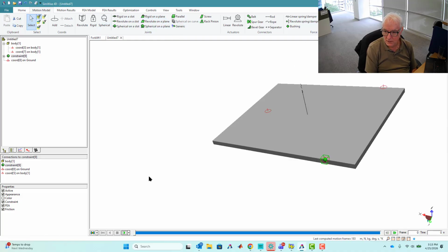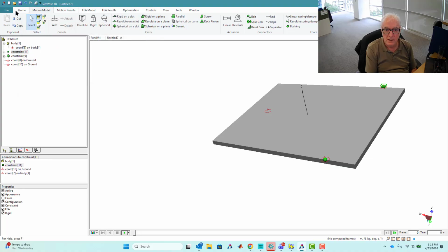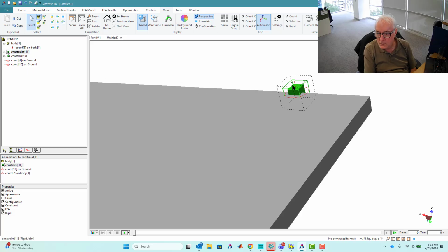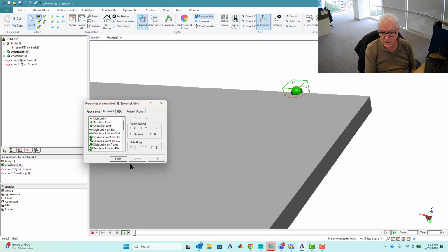Now I've referred to this, that these two will act as a rear axle. Let me prove that right now. With that frame, I'm going to connect to the ground. Let's do that right there and there. This time it'll be a rigid joint. And from here, let's zoom in. Let's turn this cube into rotation about all axes, and then let it slide along Y also.